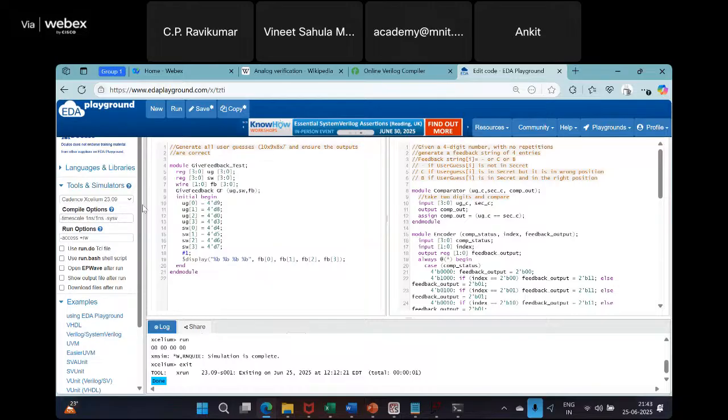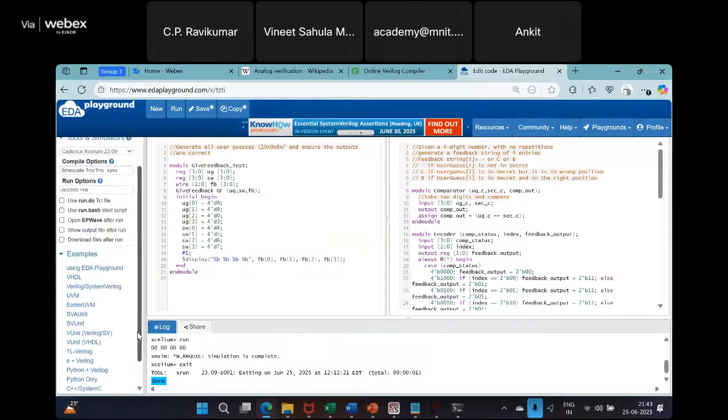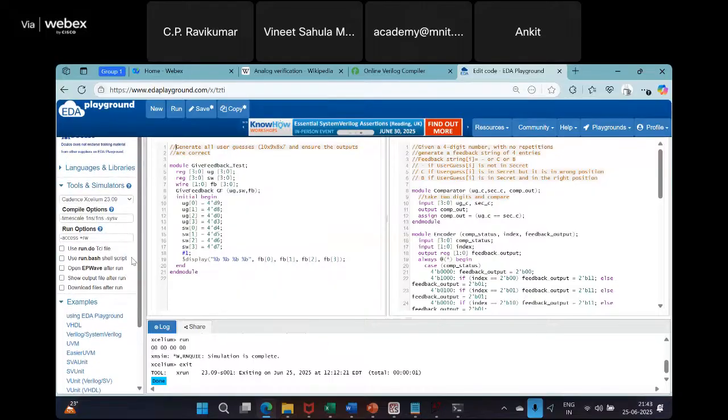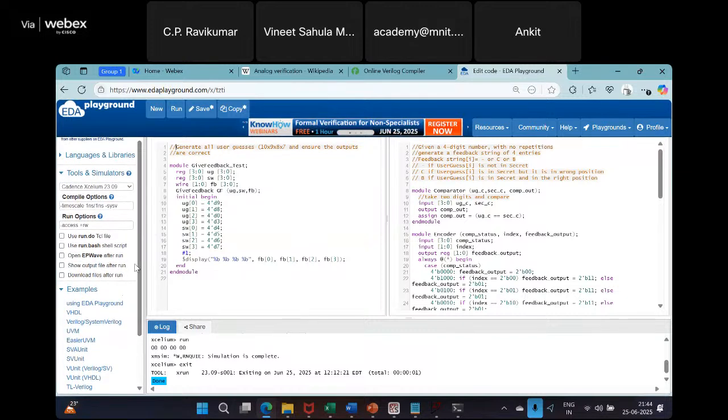And the other problem you might face is that this Icarus is not understanding. It is complaining. There are some limitations of this free Icarus Verilog. Even when you do SystemVerilog, you will realize the entire SystemVerilog is not supported by Icarus Verilog. So if your college has Cadence or Synopsys tools, you can try to use those to make this work, or you will have to rewrite it in a way that Icarus Verilog will understand. We have to figure out why it complains and see whether there is a workaround. Everybody should understand that tools are not the same.